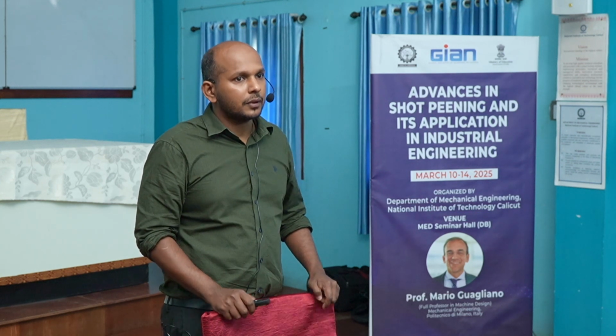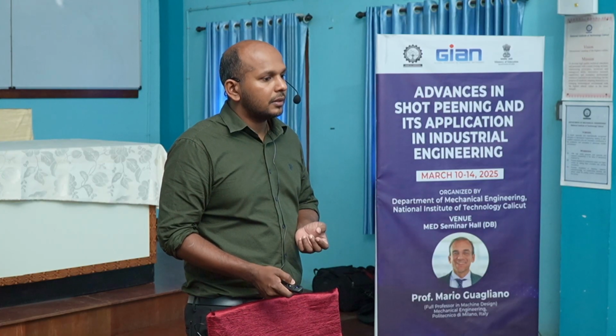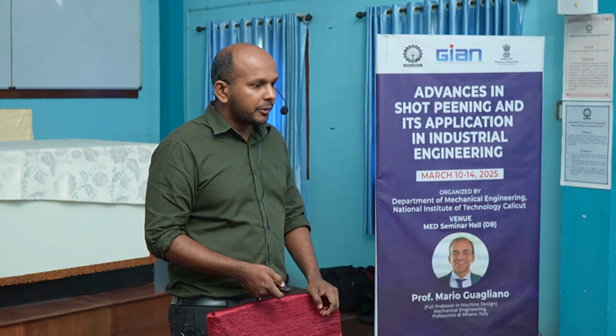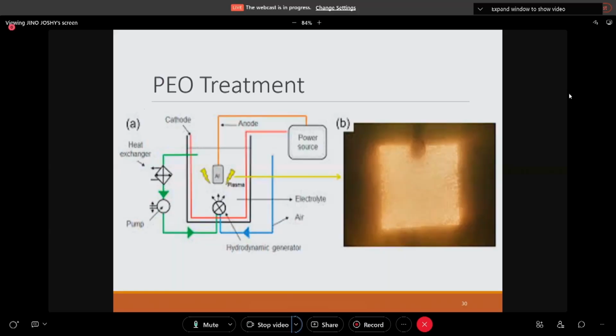Okay, sir. Thank you. Sir, could you please once more explain the PEO treatment process? PEO treatment is basically anodization only. So in anodization, what will we be doing? There will be an anode and a cathode, and we will be connecting an external power supply, and this anode will be dipped in an electrolyte.